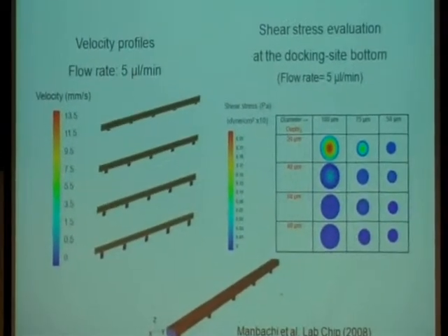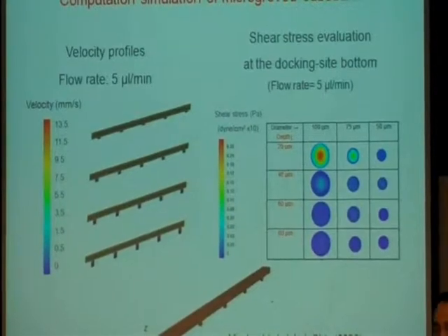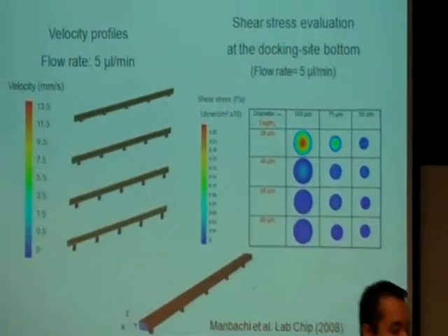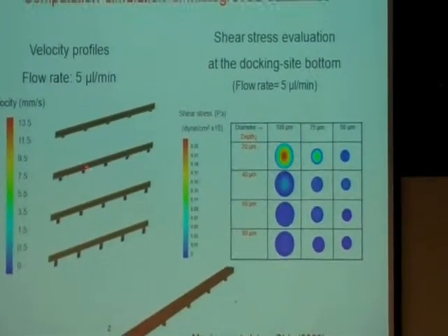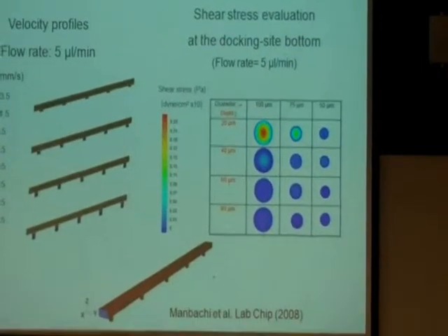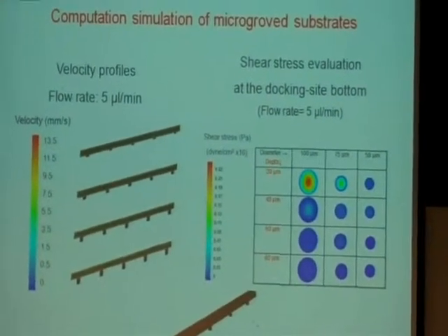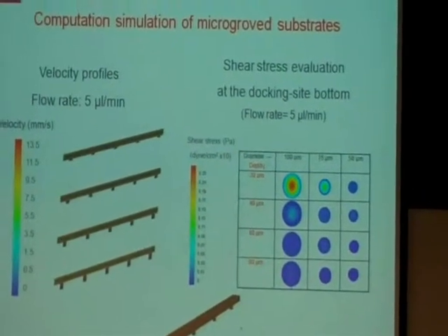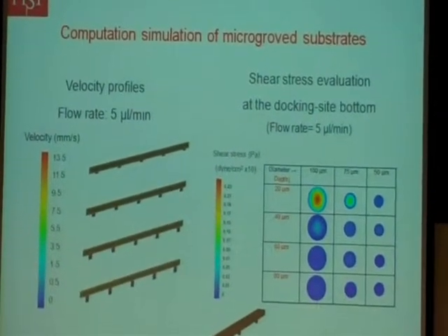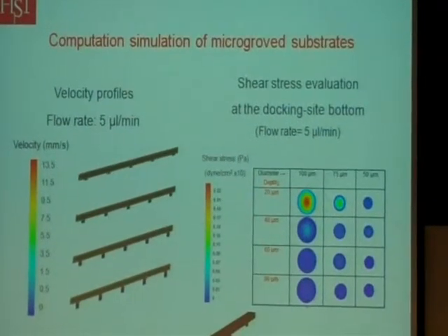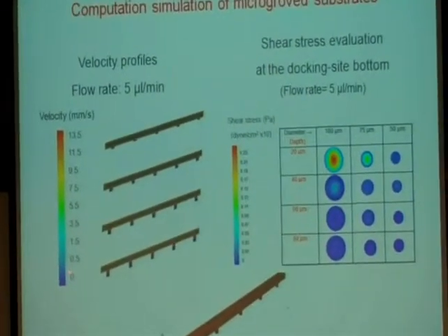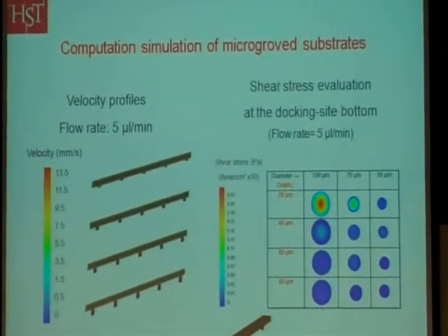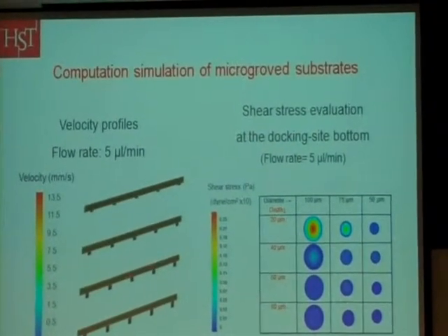So there are a lot of computational engineering approaches that one can use to understand these systems. But what I focus on is really that in these small structures, fluids behave differently than what you're used to in the large macro scale world. So for example, what you see here is that fluids can flow over these small structures, but there's a velocity gradient, so it means that these blue areas are low velocity. So basically, inside these structures, you have low velocity, and the fluids that are flowing on top skip over these little wells.